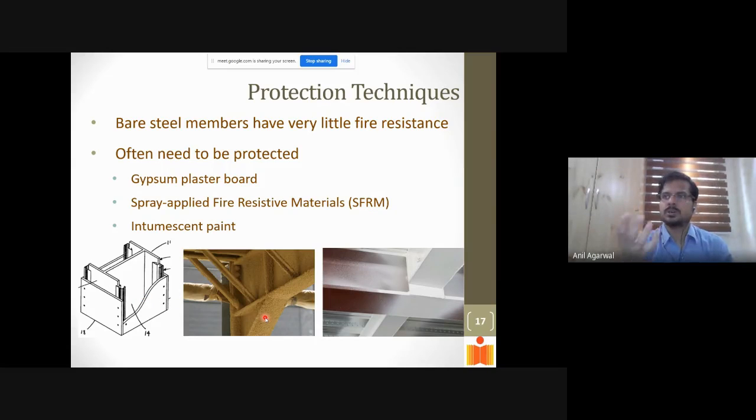But then the plaster board does not have to be thick, or meet any special fire protection requirement. You can use any kind of material on top, because fire protection is stuck to the structural member. So that's why this was preferred, because this was less labor intensive. But again, it required more work.